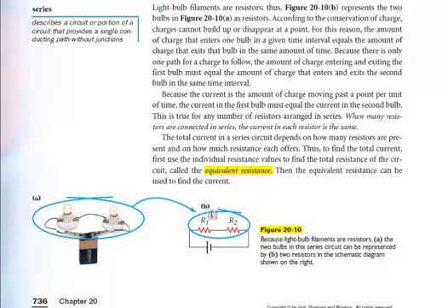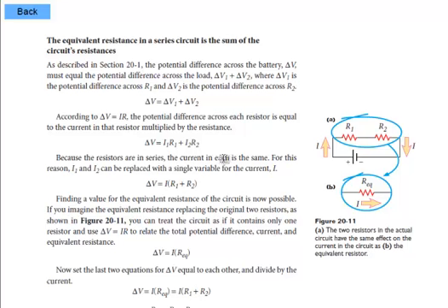That value will always be larger than the largest resistor in our series, and adding more resistors will make the equivalent resistance larger. For the same battery, that means the current is going to go down. I apologize. So putting too many resistors in a circuit for the same battery, you might wind up having so little current that things just don't work the way that they should. So equivalent resistance, make sure that you can count that.